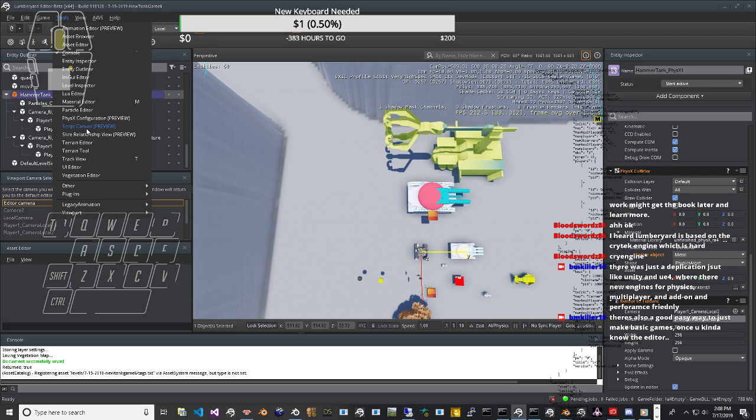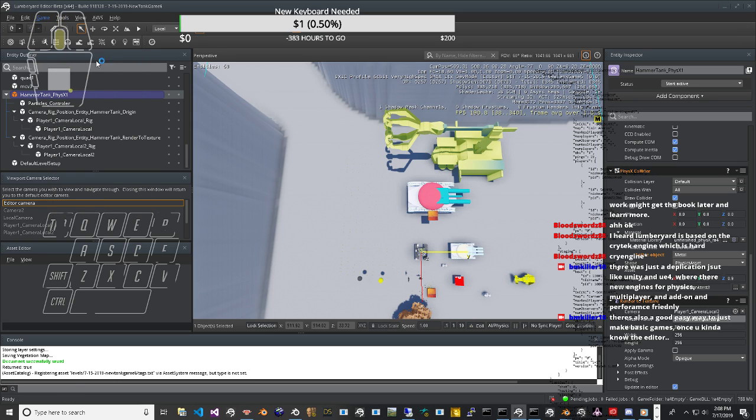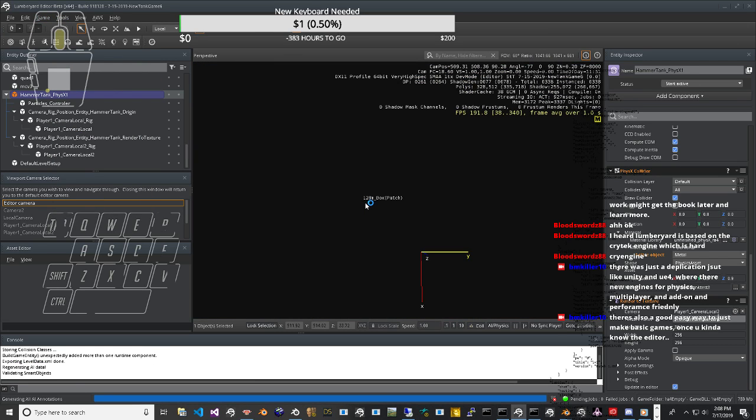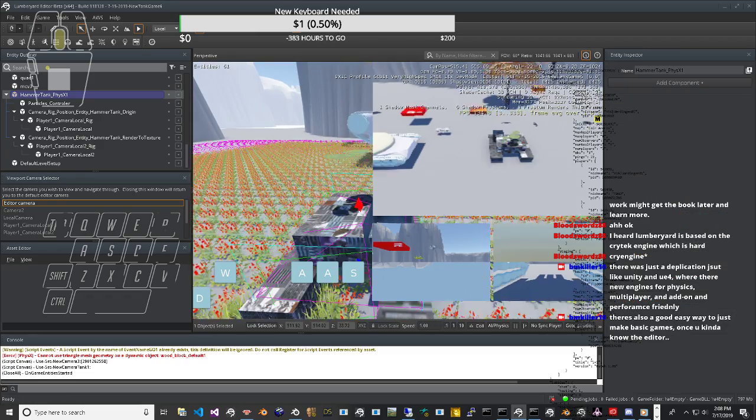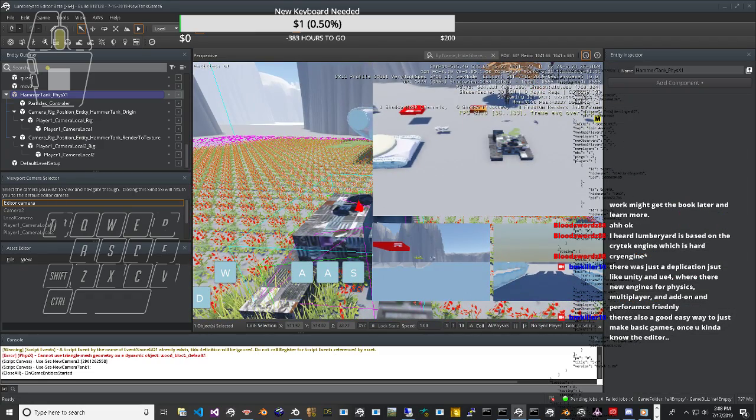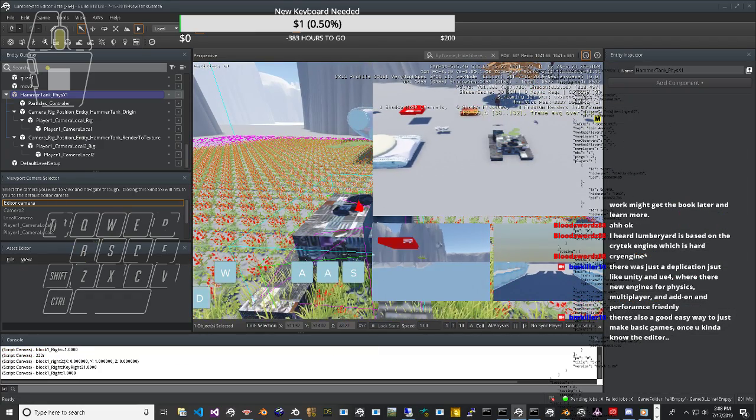This is partly correct. The pneumatic tire wheel combination does spin faster than a rigid wheel of the same unloaded radius, but it does not spin as fast as a rigid wheel of the same loaded radius, which is the height of the hub center off the ground under load. The reason is that the tire also compresses circumferentially or tangentially, setting up complex longitudinal twisting in the sidewall. The tangential speed of a particle of tread varies as the particle goes around the circumference of the tire.